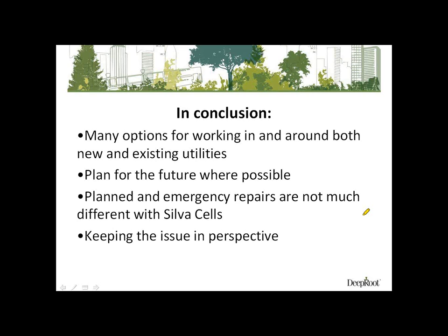In a similar line of questioning with the aggregate gap detail, we have someone who wants to know if the stone column is designed to allow roots to grow through. As this occurs, is there a risk of the roots eventually heaving the pavement in that gap area? There's always a risk of that. So I would say yes, there is.